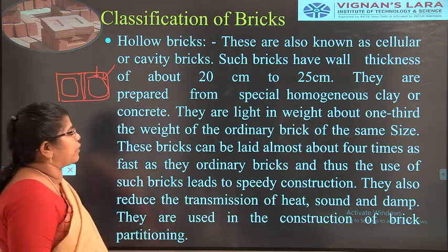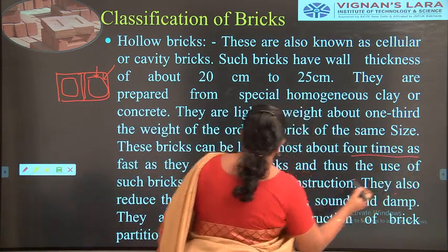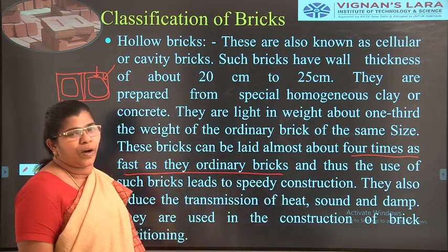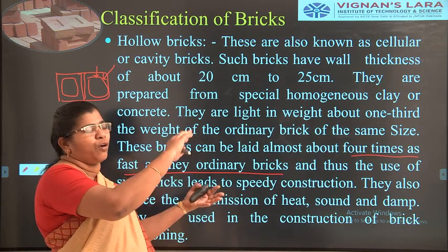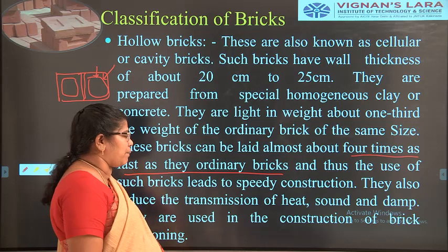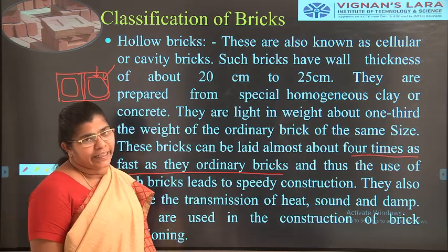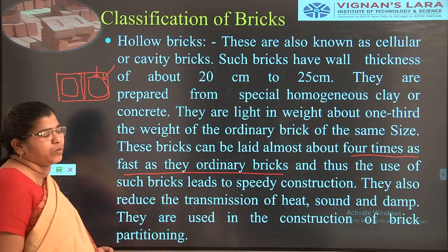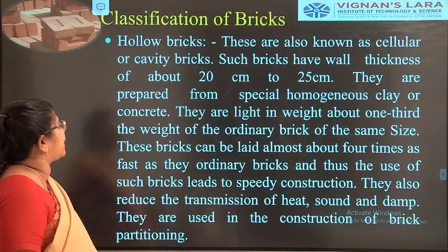Another advantage is that one hollow brick is 4 times the size of an ordinary brick, so we can place one brick instead of going for 4 ordinary bricks. The cement mortar binding areas will be less and we can go for very speedy and easy construction. It can also withstand heat, sound, temperature and dampness.